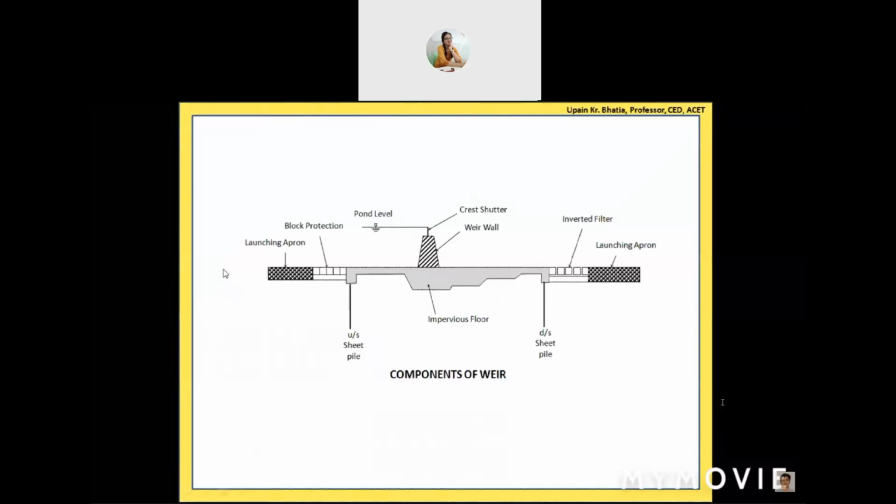So more pressure will be exerted on the river bed. That pressure will inject the water into the pore structure of the soil, so that pressure will be initiating the infiltration. And that infiltrated water will not only go vertically downward under gravity, but it will have the tendency to move from the underside of the structure and come out to the downstream side of the flow. Why?